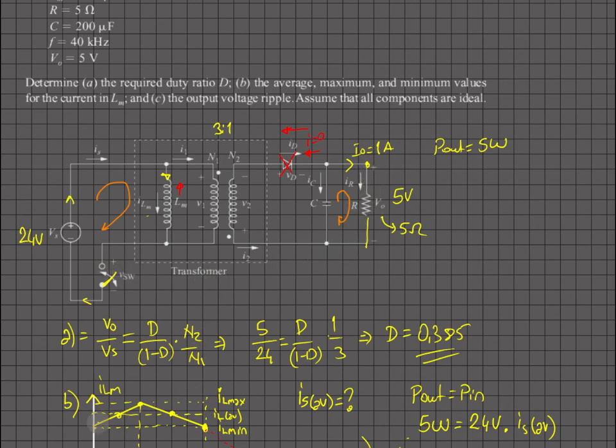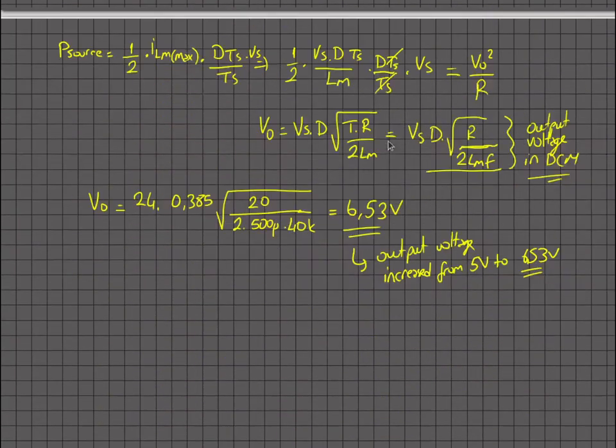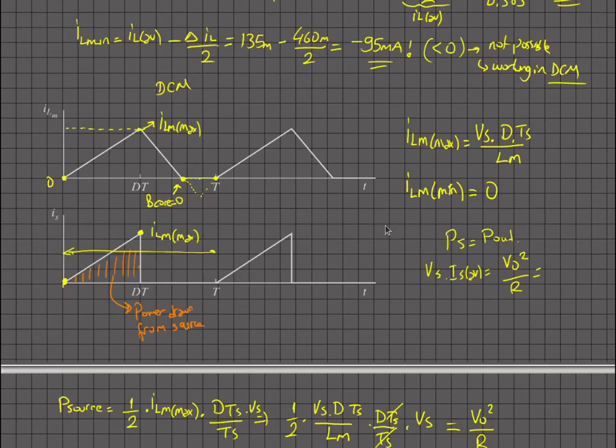Whenever the converter gets into the discontinuous conduction mode, the voltage starts climbing up, so your controller should detect that and start reducing the duty cycle to get the same output voltage. I strongly advise you to read the application notes for the flyback controllers that you may be selecting for your hardware projects.